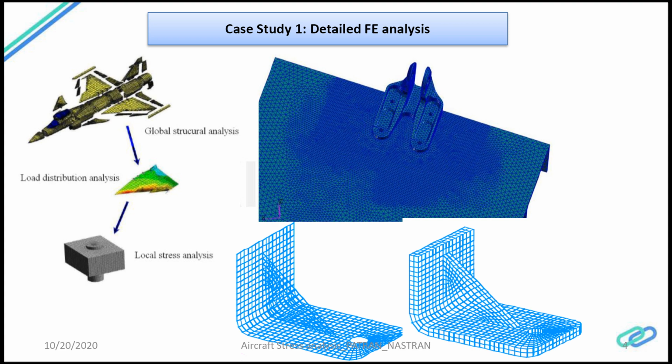Whereas if you look at the lug, the mesh is a little bit coarser, and even on the panel, as I move from the attachment area, I gradually increase the size and use a coarser mesh. Why have I put a finer mesh? Because I know that the forces will be reacting at the attachment areas when the applied force is acting on the panel. The attachment is only through the lug.